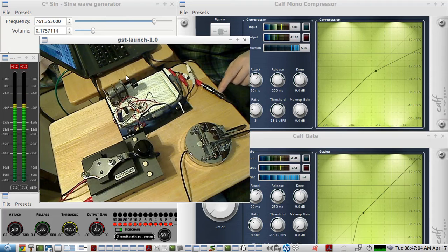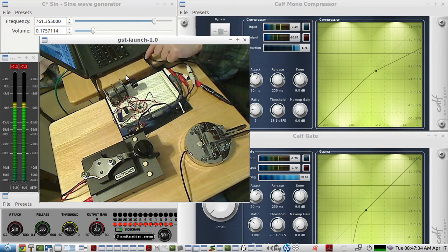So to get that voltage to this condenser mic, which is a headset mic, you need this stereo to mono adapter, which takes a 1/8 inch stereo to a 1/8 inch male. And then to get to the RCA, you need another adapter, which is a 1/8 inch female to an RCA male, which goes to this breakout splitter. And that plugs into the mic jack.